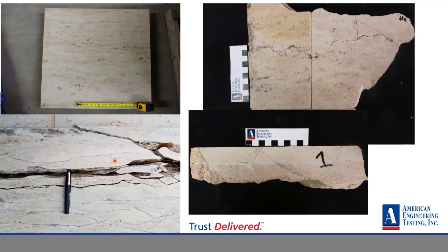And apparently this stone is known to be very resistant to weathering, but the engineer in the field did say that there was bad engineering on site, like poor drainage. The homeowner never shoveled snow. It was in a climate where they got a lot of freeze-thaw cycles. So if you're not shoveling your snow, that snow is melting and then maybe freezing overnight, melting, freezing overnight, and gets trapped in these planes of weakness that we see. It can cause big problems.